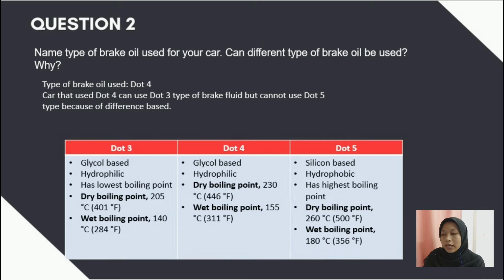DOT 3 and DOT 4 are glycol based, but DOT 5 is silicone based, and it is also hydrophobic, which means it doesn't absorb water, so it is not compatible with other brake fluids such as DOT 3 and DOT 4. If we mix DOT 5 with the other two types, it will cause the brake to malfunction due to their incompatibility.